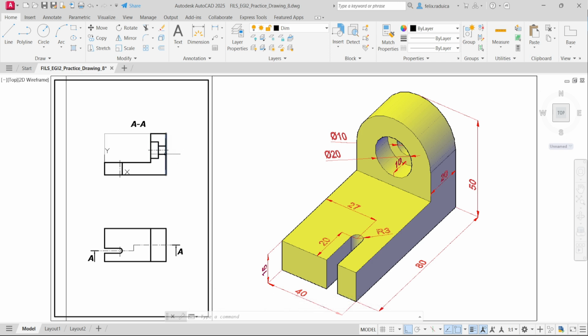So this is the inside smaller hole, which is of a diameter 10, and this is the outer larger hole of diameter 20, and then there is the outer part, which is of radius 20, and that is derived from this dimension of 40 here. I split that into 2, divided by 2, and found the radius of that.